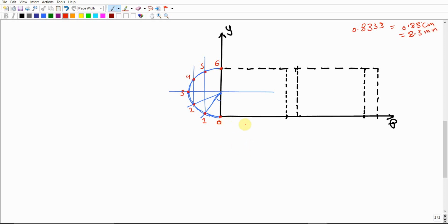Every division is going to be approximately 8.3 millimeters, or you can mark a point just beyond the 8 millimeter mark or dash on the ruler or the Aristo triangle. So your objective is to break it down into around 8.3 millimeters each. And this is what we're going to do. I'm just going to measure here, starting from the 0 point.